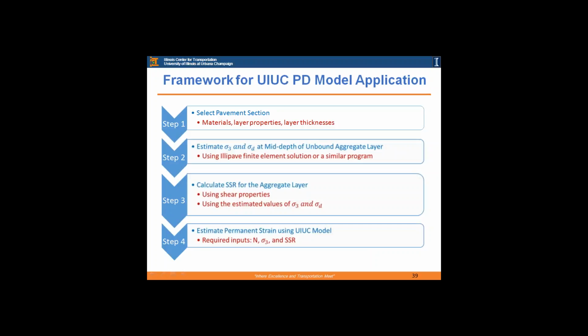The previous results for moisture density were actually provided by NCDOT, and they were run at the source gradations. So we saw some slight differences between the maximum dry densities and the optimal moisture contents, but they were not very high. And those are the values that were used to prepare the samples for the engineering gradations that were previously done.